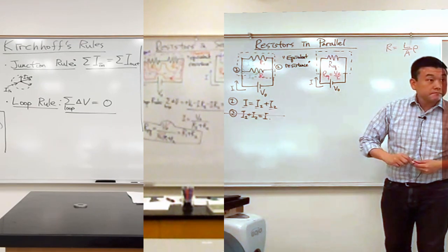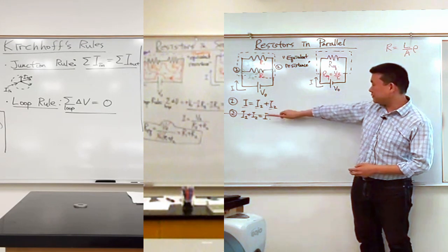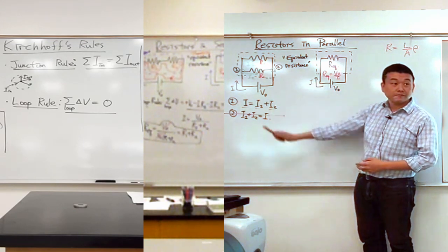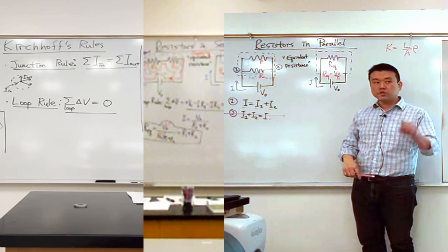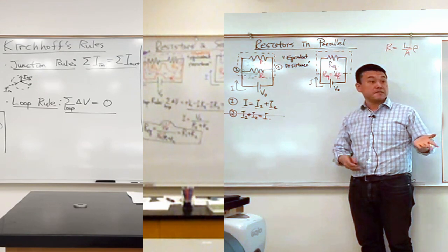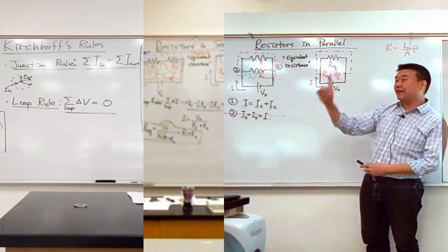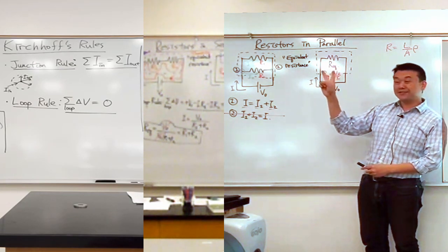Is it dependent on which junction you use, or it doesn't matter? Doesn't really matter. I mean, I could have used this junction and kept this and got rid of this one. Cases like 3 and 4 junctions. Yeah. So as long as you leave 1 unused, you will be guaranteed to have an independent system of equations. Independent, but not enough. I only have one equation. I need two more, at least two more.